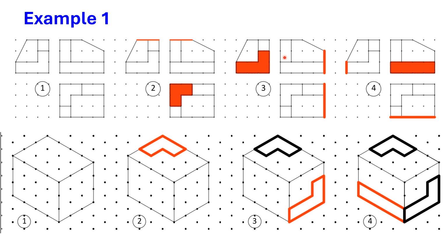In the third step, again you identify any other surface. As we already completed this surface, now let me go to this side view surface, that is like an L shape. This L shape in the front view is coinciding over here. It is not coinciding here because this length is more and this length is only 20 mm. It is only coinciding at this side. This same principal surface is coinciding in the top view here, because here only 20 mm is there, but in the top view it should have 30 mm.